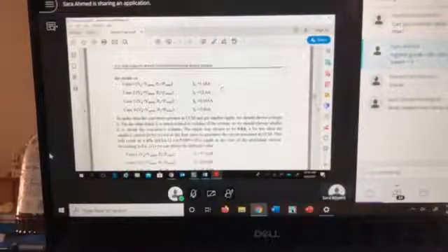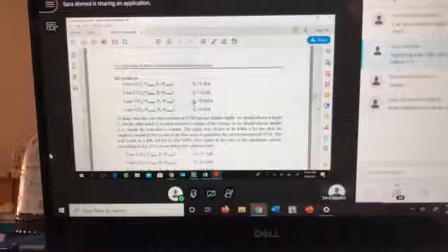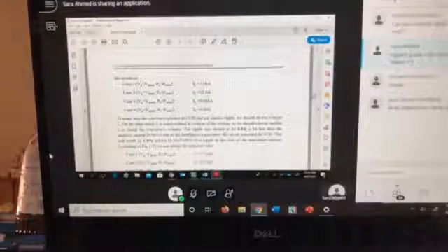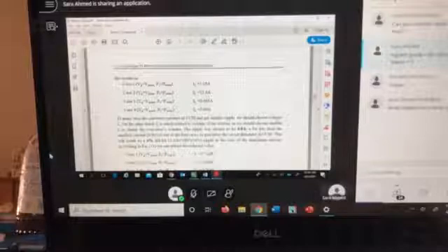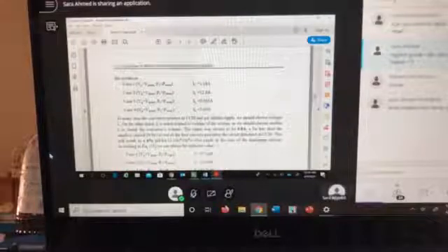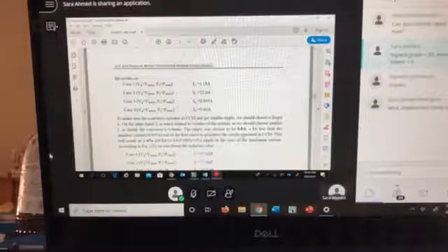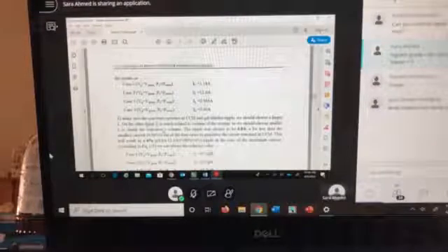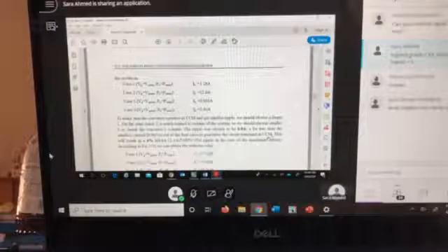So if I want to make sure the converter operates in CCM, then I need to choose the smallest I of L here and choose my ripple to be less than that. So again, it tells you what? The ripple was chosen in this case to be 0.8. You can choose any number you want because it doesn't really give you a certain number. But it has to be smaller than the smallest current out of those 4 cases so that you can guarantee that you stay in continuous conduction mode. Okay?